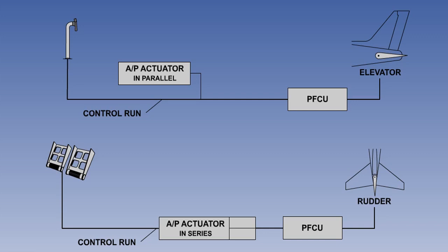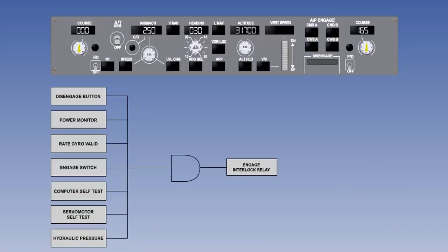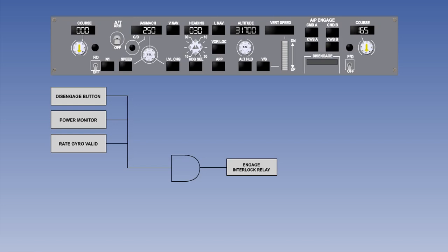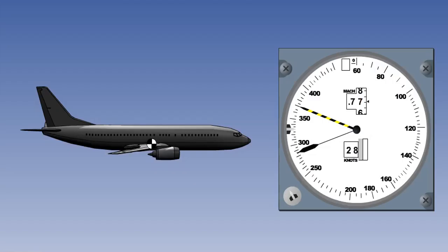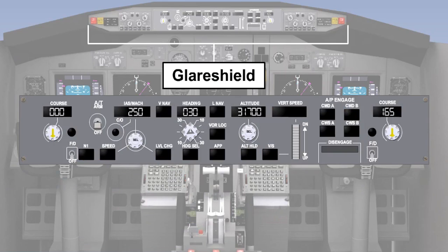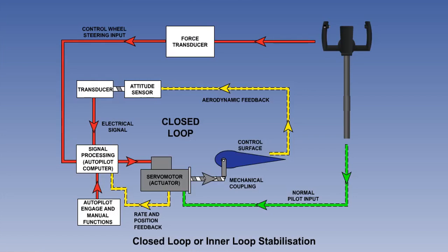During this lesson, you have learned how the autopilot moves the aircraft's control surfaces, the interlocks that have to be made before the autopilot will engage and remain engaged, and the reasons it will disconnect. Next, you were shown AutoTrim, which is an autopilot function, and MachTrim, which is not an autopilot function. And you studied the pilot-autopilot interface, the mode control panel. Finally, we considered the control wheel steering, which allows the pilot to use the control column to control the autopilot.